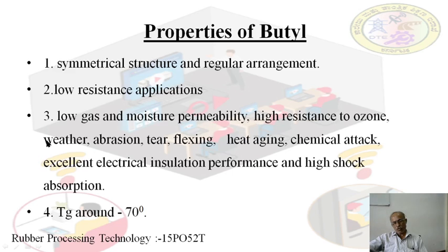High resistance to ozone, weather, abrasion, tear, flexing, heat aging, chemical attack, excellent electrical insulation performance, and high shock absorption. Fourth point, glass transition temperature around minus 70 degrees.